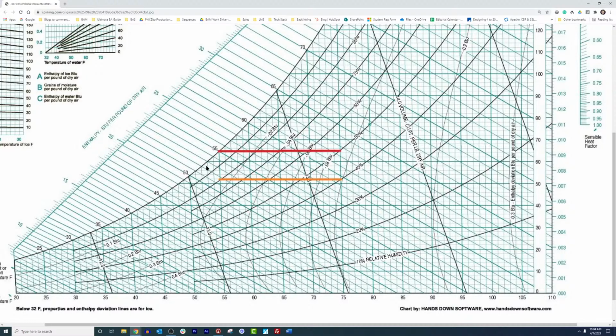In the case of a VAV air handler, we're driving for that 55-degree DAT because in reality, we're at anywhere from 48 to 52 at the coil. So when we're leaving the coil, we're at 48 to 52 degrees, and so we're wringing the moisture out of the air.